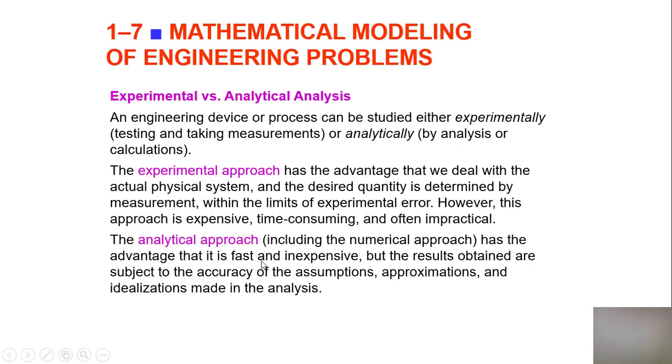Then the other thing that we have is analytical approach. This one is fast and inexpensive, but the only challenge is that the results that we get are approximations, because we are mainly working with assumptions and coming up with ideal situations. So some of the definitions that we're talking about, things like steady flow, incompressible flow, one-dimensional flow, all those are assumptions that we are going to use to solve our problems, because in this case we'll dwell much on analytical approach to do the actual problem solving using pen and paper. It's also important to use analytical approach, though it has these setbacks, like we are using a lot of assumptions and approximations, so your answers might not be close to the ideal situation.